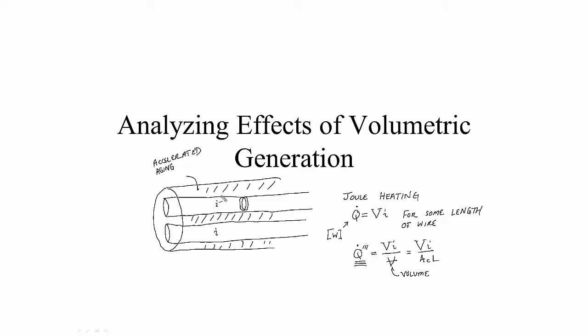As you expose them to higher temperatures because of overcurrent or over voltage within the conductors, within the wires, you start to degrade these systems. And as you degrade them, when you start to bend and fold them, you actually can completely fail them. And as you fail them, and there's less and less of these things available, you can get an arcing process, and that arcing process would lead to a fire.